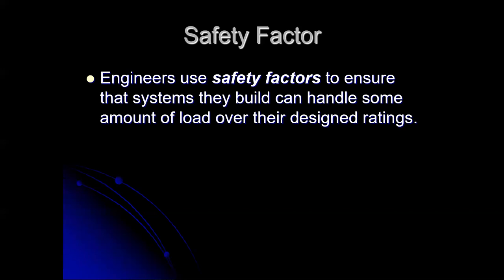Now, that amount of load that we can handle over the designed rating is not something that people are usually allowed to take advantage of. For example, in loading an airplane, typically the wings are designed to handle 50% more load than what they state is the maximum gross weight of the airplane. Just because we can handle that load doesn't mean that we get to legally load the airplane up to that level.